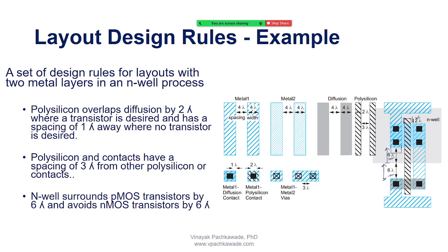Okay. Why that extra metal contact, sir? Where? Here, this one? No, the metal contact. This one, right? Yeah. So generally, the physical reason is that we have drawn the size of the PMOS like this. This is PMOS, and this is NMOS. So we are saying that the width of a PMOS is greater than the width of an NMOS.